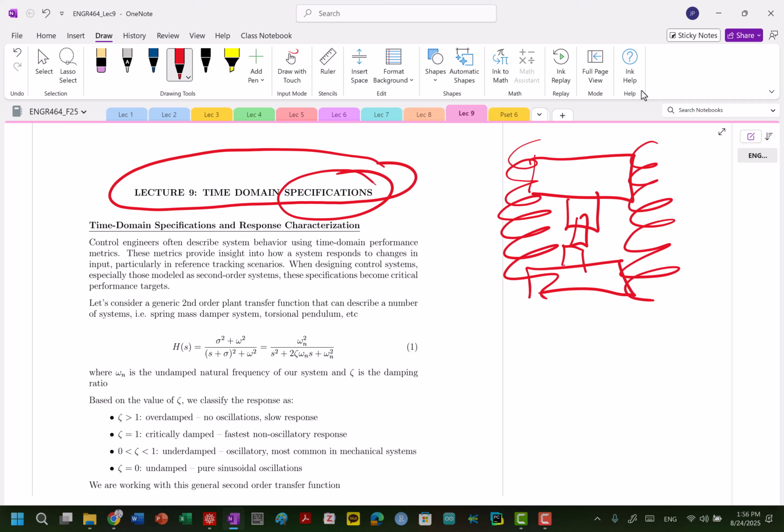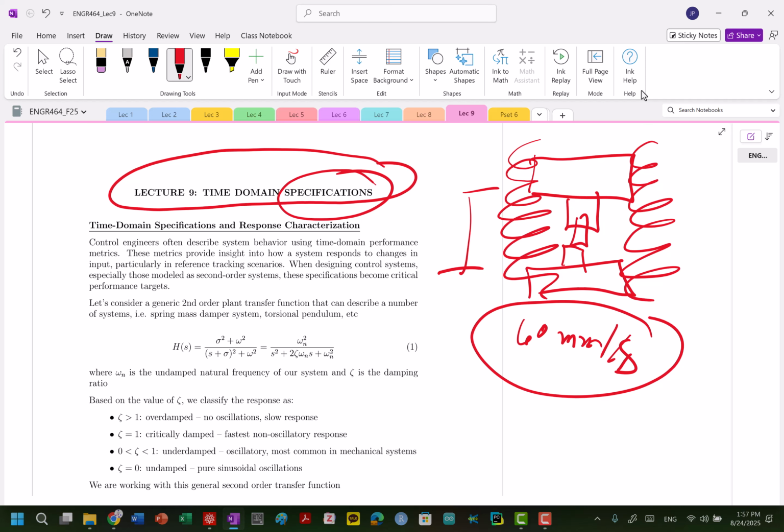So if I'm designing a control system, something like this, I'm going to want certain specifications, right? Like if I need to measure, I need my displacement rate, the displacement rate of essentially my grip distance, to be something like I need to run at 60 millimeters per second. Maybe that's my top end specification that I need to hit. Maybe I need to have a resolution or a step size, I need to be accurate to 0.1 micrometers in terms of my displacement.